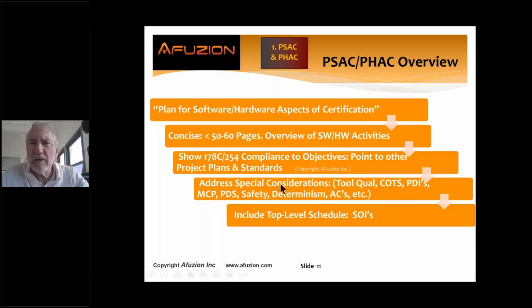And then of real concern, folks, and we're going to address this in the mistakes and best practices, we need to pay attention to technology that potentially changes, affects, maybe subjugates our certification. What tools are we using? Are they criteria 1, 2, 3? Criteria 1, development tools that could cause an error. Criteria 2, a hybrid tool, verification plus a reduction, automation, or replacement step of verification. Criteria 3, are we reviewing the output of those tools? If not, qualify. You don't do both, too much money. You pick one, we'll talk.